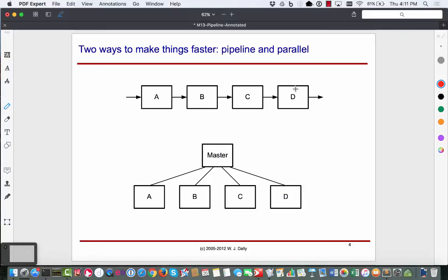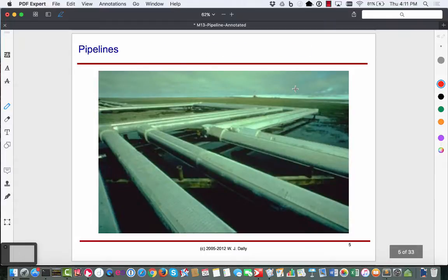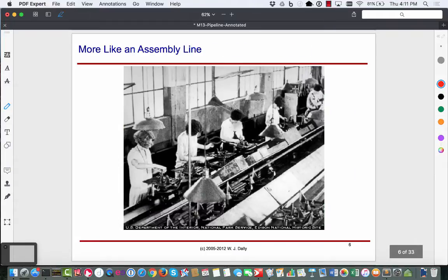Parallelism sort of offers complementary advantages. So the assembly line analogy kind of holds true that, faced with a computation task where I have to do a sequence of things, and we already encountered many cases where we were doing a sequence of things, like our adder was like that. We first did bit number 0, then bit number 1, then bit number 2, in a sequence like that. And since they were in a sequence, I could not do them in parallel. I couldn't do bit 0 and bit 1 and bit 2 in parallel because I had to wait for the result from the previous stage.